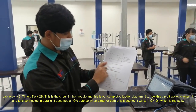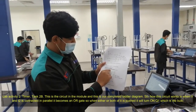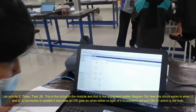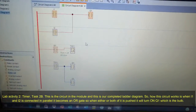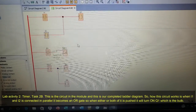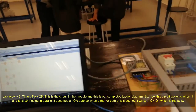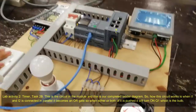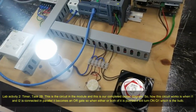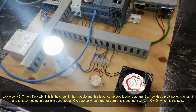Lab activity 2, timer, Task 2B. This is the circuit in the module and this is our complete ladder diagram. So how this circuit works is when I1 and I2 are connected in parallel, it becomes an OR gate. So when either or both of them are pushed, it will turn on Q1, which is the bulb.